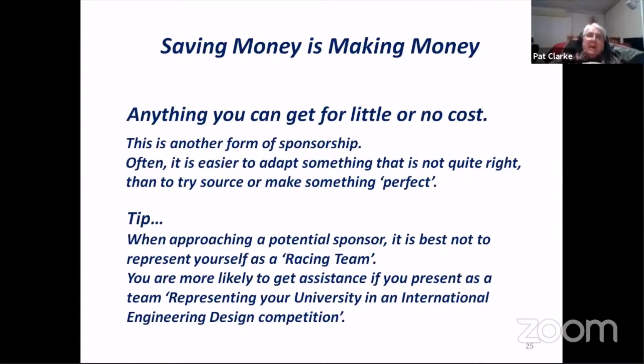If we go back to steering wheels again, almost every student-made steering wheel that I have seen in a Formula Student car is too small. Their experience with steering wheels usually comes from simulators, games and game simulators, and they have these little steering wheels that look like a mini Formula One steering wheel. But there is so little leverage available in these small diameter steering wheels that after about 4 laps, the poor old driver's arms are falling off, and you can't complete the laps and get a good performance in the dynamic events, especially the endurance event, if the poor old driver's arms are cramped and he can't move another inch. Whereas when you go buy a steering wheel, it will probably be a 13-inch steering wheel rather than a 10-inch steering wheel that the teams insist on making.